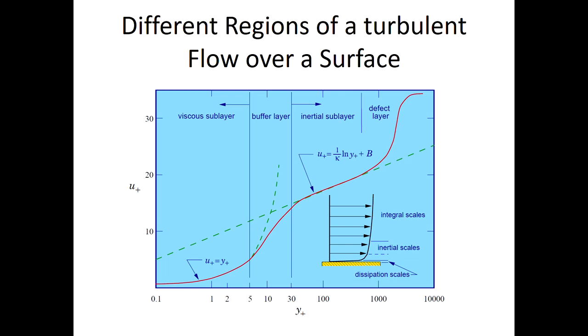So this region is very close to the wall. It's called the viscous sub-layer. Then we said the next layer is called the buffer layer, where both the molecular diffusion effects and the eddy diffusion effects are present. So the shear stress from the molecular effect plus the Reynolds stress from the eddy together will become a constant called shear stress at the wall. Then out here, the molecular stresses are very, very weak. So we are going to start looking at this region next.